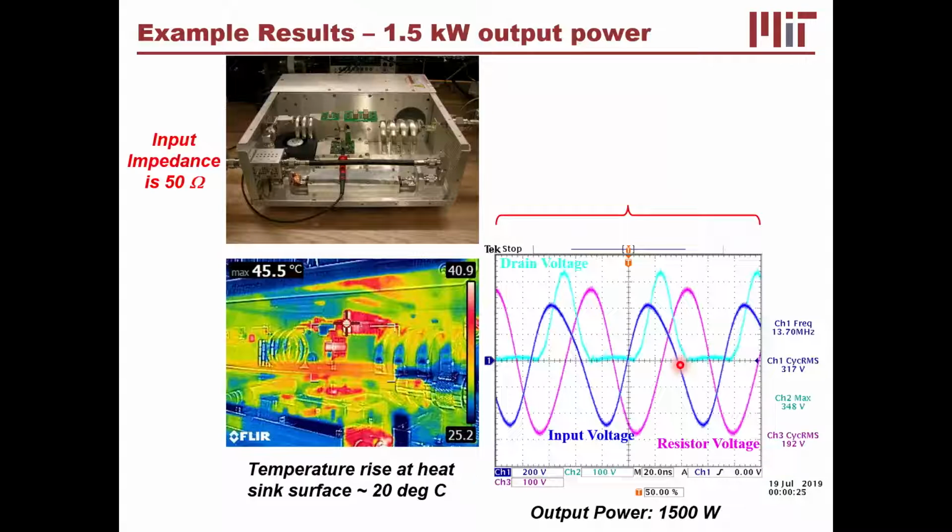All right? The result of that, as I said, we had 100 and something watts of heat dissipation in the worst case. But if you look at the temperature rises of the thing, the heat sink surface only goes up 20 C. Why? Because we've got crazy heat flow. Right? So this is the kind of thing you do, and we used exactly these models to figure out the thermal resistance from the junction to the case. Then we had the case going down to the heat spreader, and it was soldered, so that's pretty low, and the heat spreader to the heat sink, and the heat sink to ambient, we looked up from the data sheet, and boom, we have our model, and we have our nice thing where we can pour lots of dissipated power into it and still keep it cool.